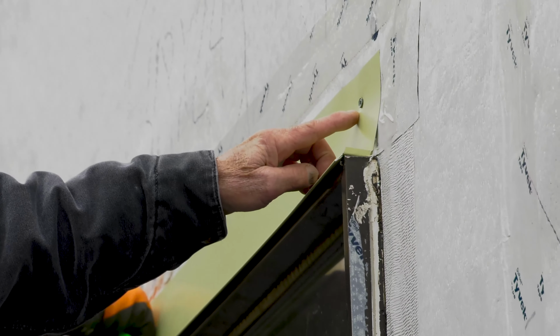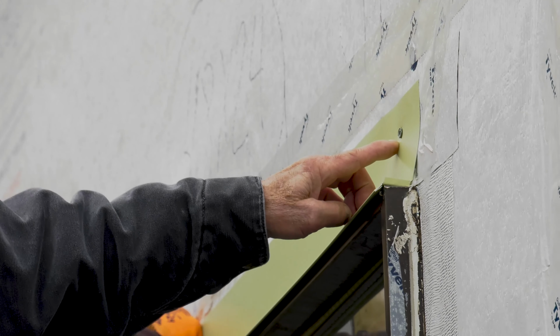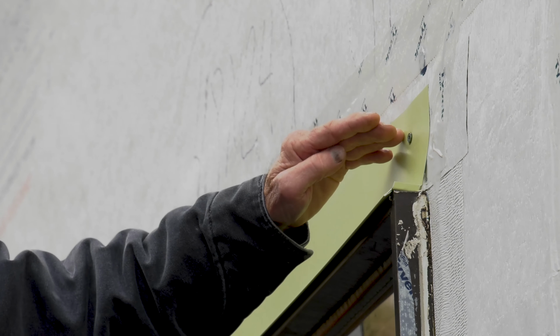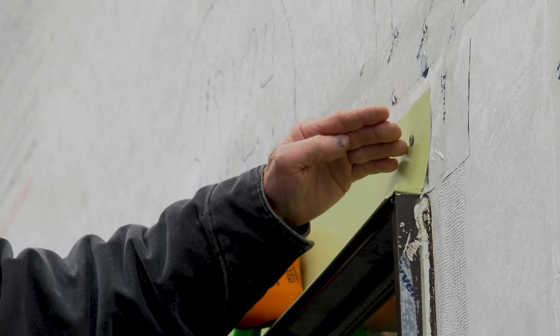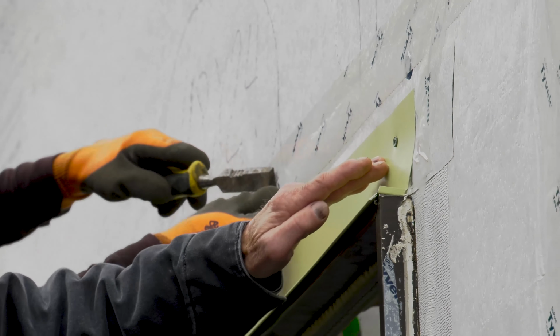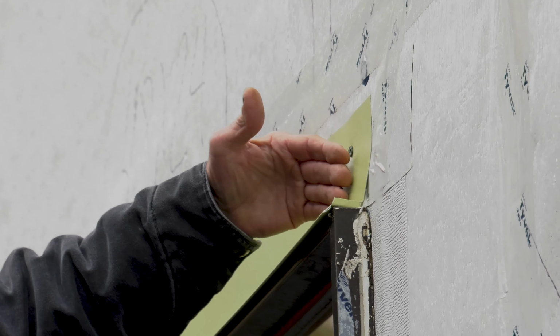So our crew has just applied the fasteners for our high back flashing, and we hold those up high so that when we incorporate this into the weather barrier, these are up out of the window flange area, and we can incorporate the proper weather barrier over the fasteners.